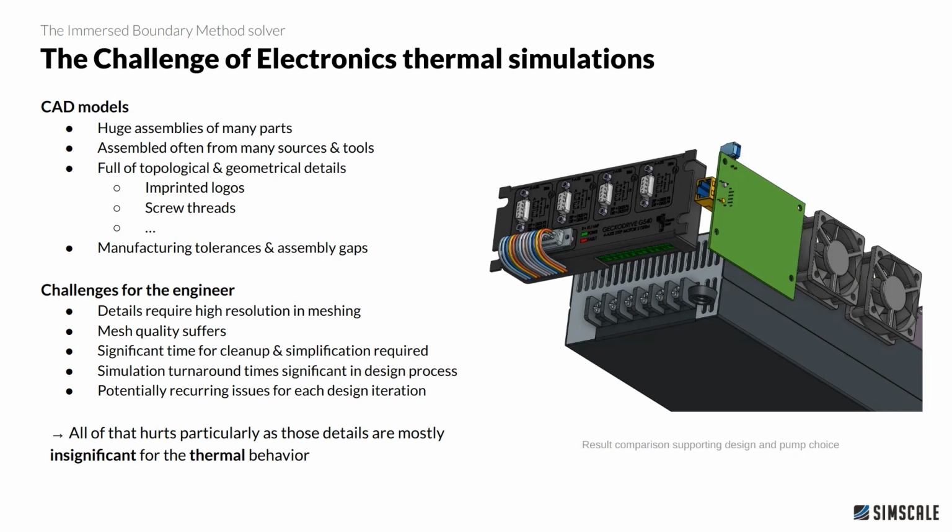So even though you're not interested potentially in the areas where these details sit, you still need to really resolve them for the whole system to be solved in a stable way. That's really a pain, right? And that means essentially that you can pick if you go very, very fine, spend a lot of time in meshing, or if you spend a lot of time in simplifying and cleaning up your CAD model, and that can be easily a longer time frame than the runtime of the simulation. It can be hours, can be also days. That's really, really painful time that gets lost in the design workflow.